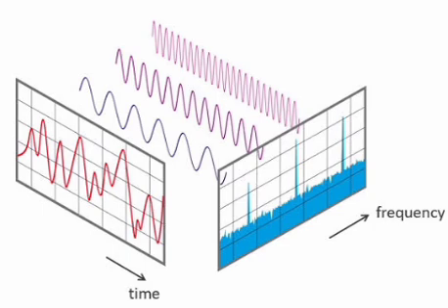If x[n] is two-sided and the circle |z| = a is in the ROC, then the ROC will consist of a ring in the z-plane that includes the circle |z| = a. For the unilateral transform, X(z) = sigma n = 0 to infinity of x[n] z^(-n). Left shift: x[n+1] corresponds to z X(z) minus z x[0].